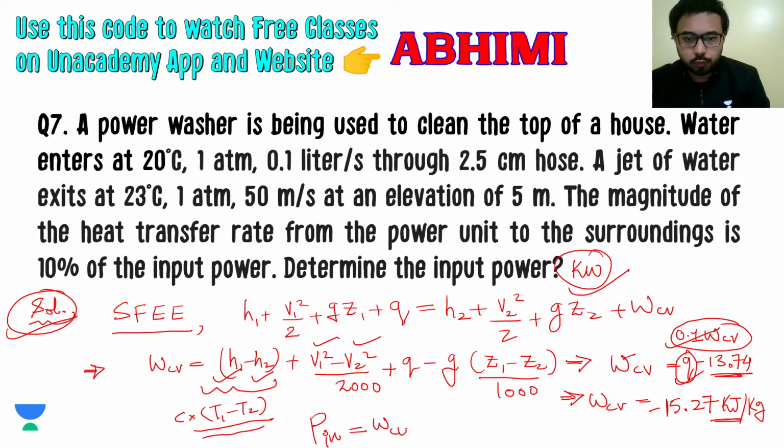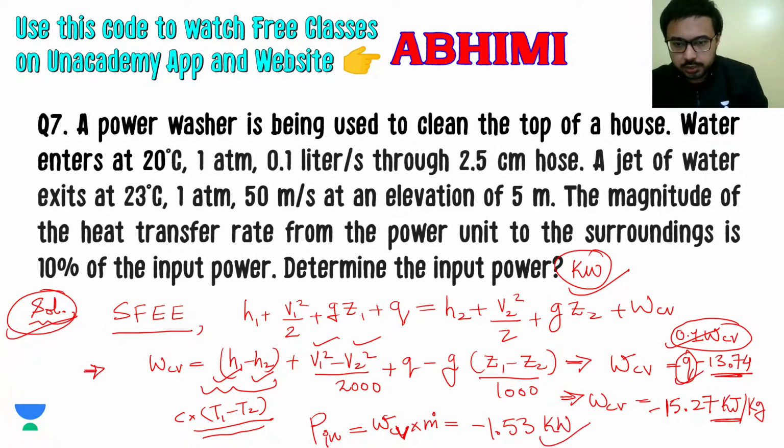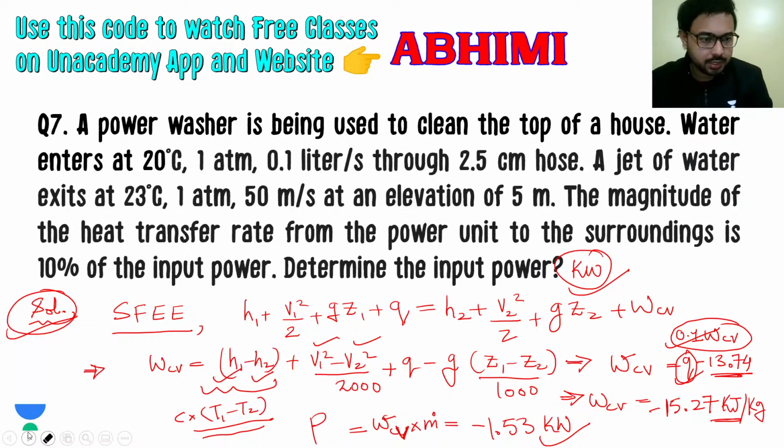So it will be work of the control volume times the mass flow rate, which is nothing but 0.1, so just multiply it with 0.1 and we can get the answer as minus 1.53, let's say, kilojoule, or not kilojoule, kilowatt. And since we have to answer what is the input power, we will not answer it with a minus sign, because input itself means the minus sign, or let us write here not input but work of the control volume, because input means that the minus sign should not be written.